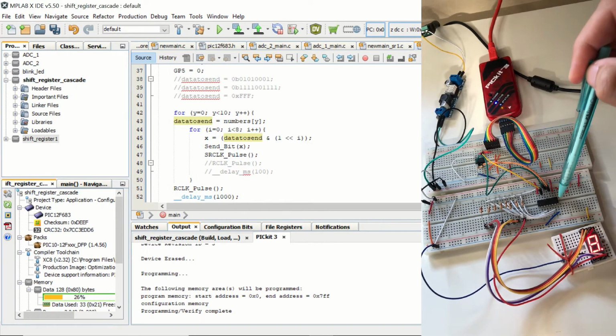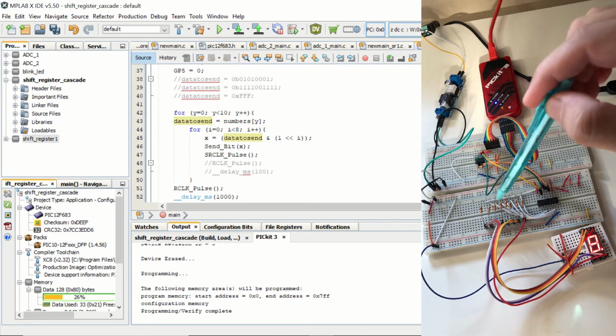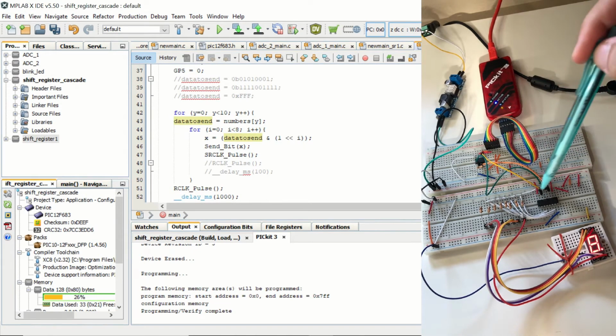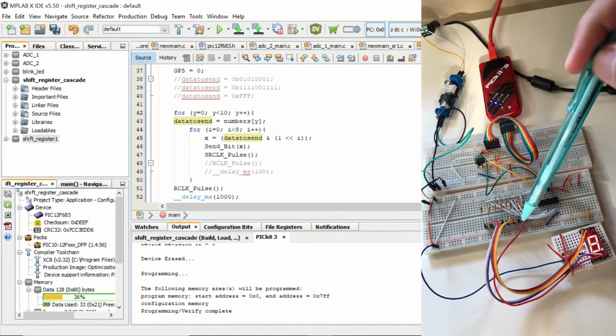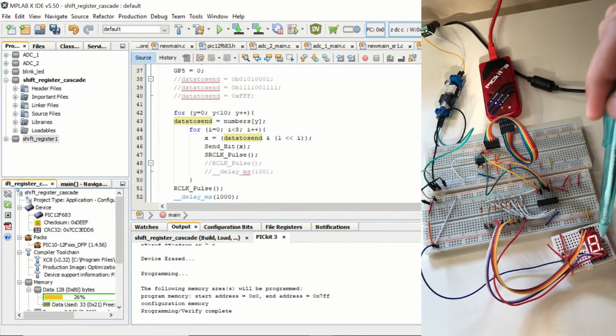And from the shift register, we have 8 current limiting resistors. And from those resistors, we are connecting the jumper cables. We have 8 jumper cables, and those are connected to the 7-segment display, as we saw on the diagram. So at this moment, all of the LEDs are on, and now we are going to do some modifications on it.